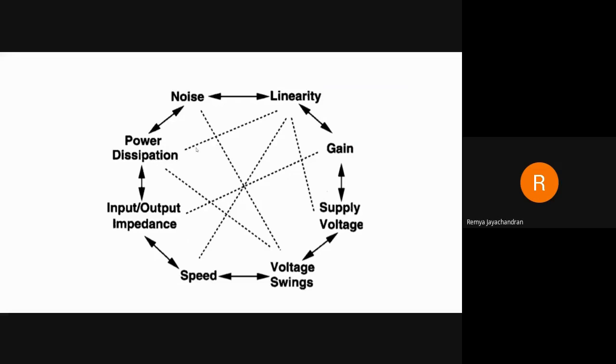And you can implement your circuit. For the analog IC, you can see that analog IC design differs greatly from digital IC design. In digital IC design, it is mostly done at an abstracted level with systems and processors that determine the specifics of the gate or transistor level, placement and routing. Analog IC design generally focuses more on the circuit, especially on the sizing and the specific parameters of each transistor.